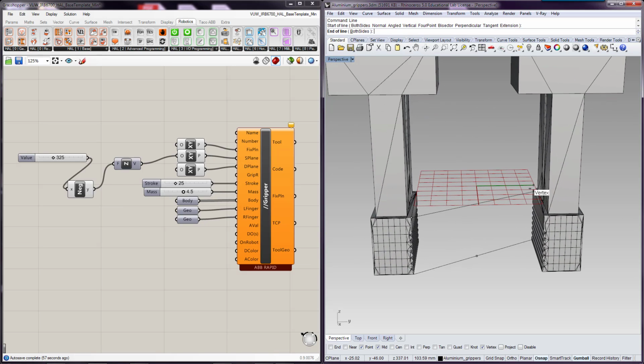One drawback could be that you're not actually snapping to the right geometry, which is what's happening here. Another drawback could be that since it's going to be dependent on points or actual geometry, if that point or that geometry moves and you don't move it, or you don't know it, or you move this geometry and you don't move the point with it, you won't know.